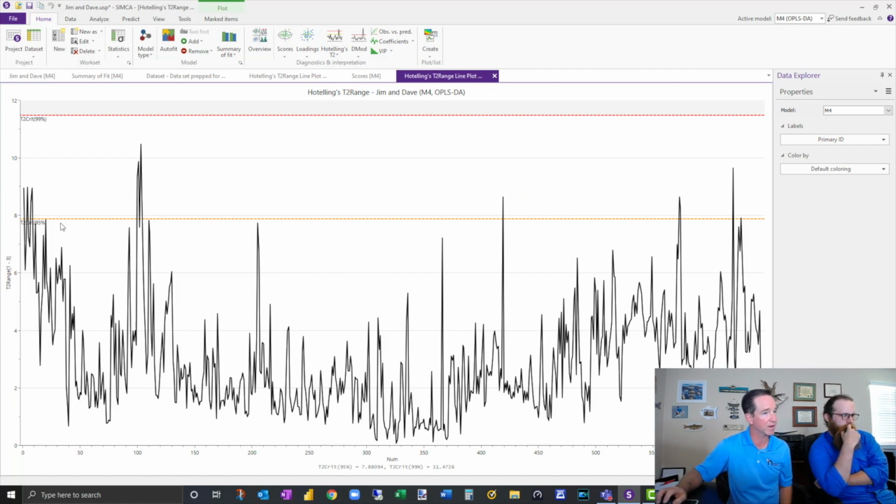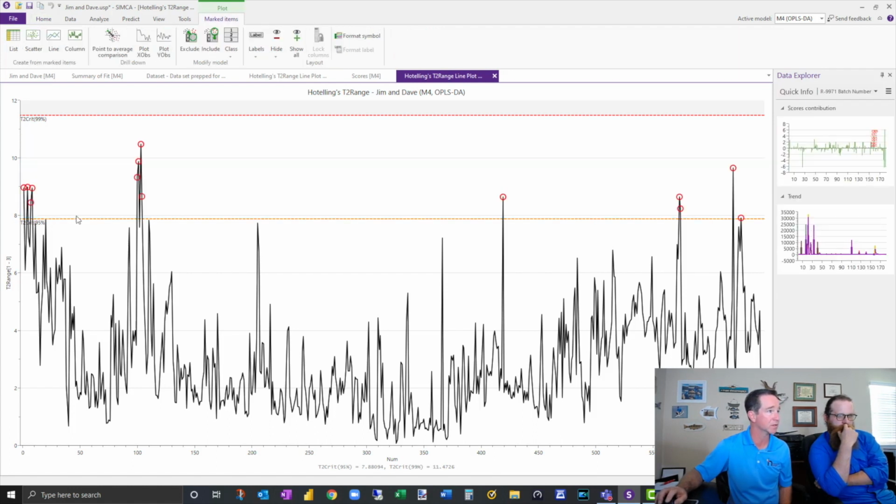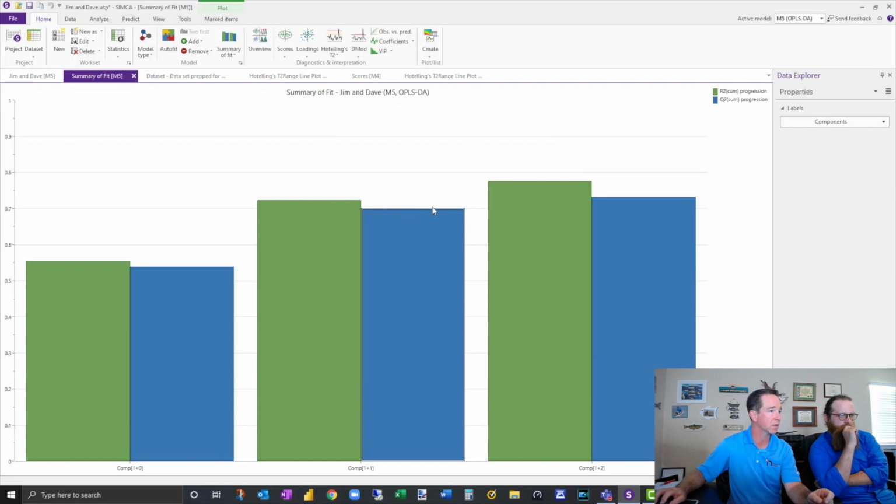If I want to get below 95, I guess I could do that. Let's just try that. I don't think I did that on any of my runs. So I can exclude this. Basically, we're just getting rid of outliers here. Now I've gone from 680 rows of data or observations down to 631. I'll auto fit that. Again, staying at a pretty good 3 components.